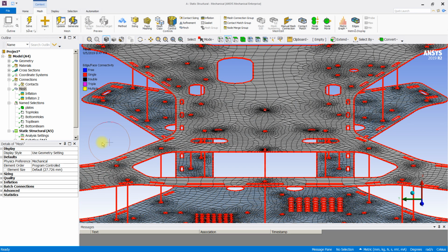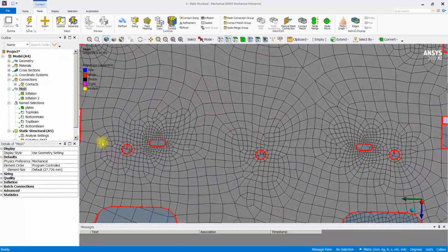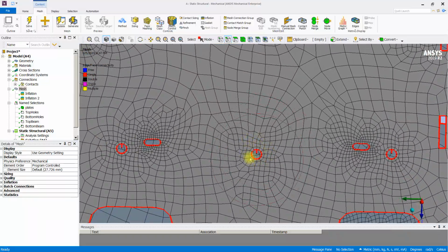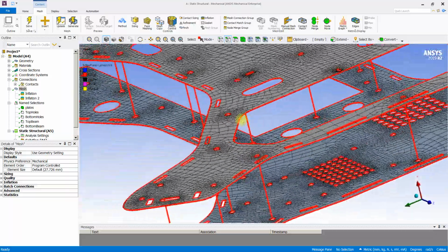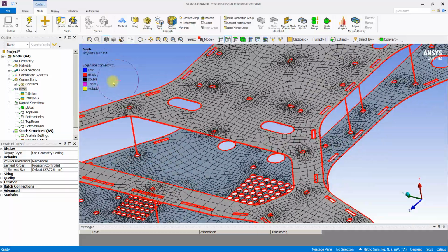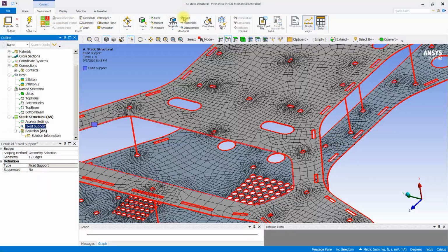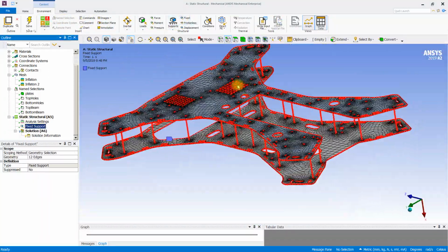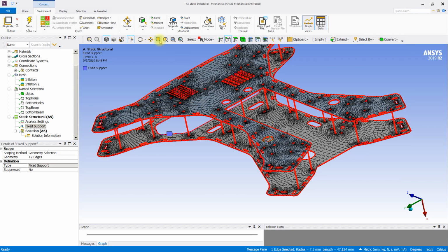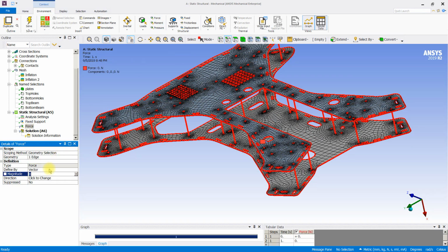So here's the... and you see you have a nice little 1 millimeter ring around each hole. So just to finish up the video, we'll go into the static structural, we'll pick an edge and we'll extend to limits, and we'll call that the fixed side, and then maybe on the other side here we'll pick a hole and we'll apply a force of 100 newtons to that hole, and maybe we'll flip that down.